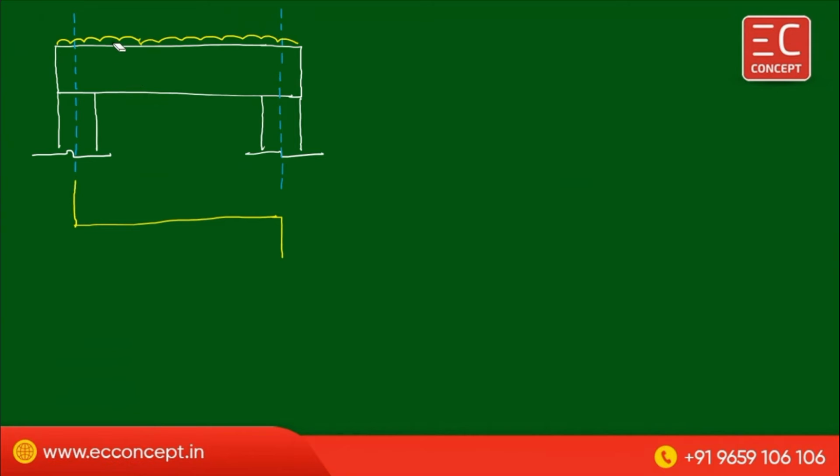Moreover, as per assumption, this is the length up to which your load is acting, W kilonewton per running meter, and this is the center point and the way in which the shear force is acting. And the code says d distance from the face of the column is the critical section. So this is now the critical point, from the right support.